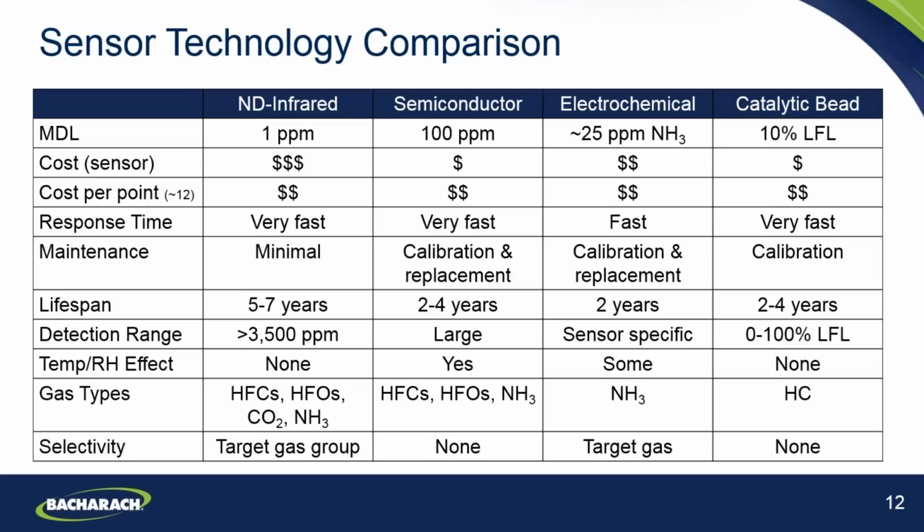If we look at this with a fairly high air exchange rate per hour of 5 air exchanges, taking the view of this being a fairly typical machinery room application with a lot of ventilation happening within there. If we have this 20% annual leak rate happening within that environment, we can see that the distributed and diffused level of refrigerant leaking into that space will never actually go above 7 parts per million.